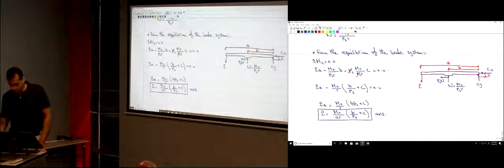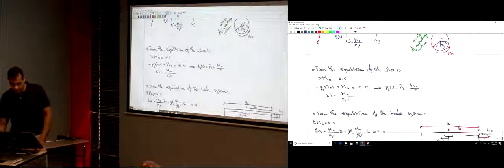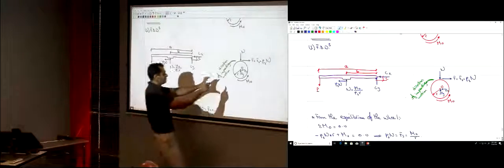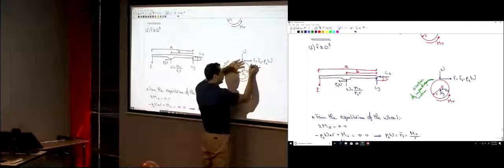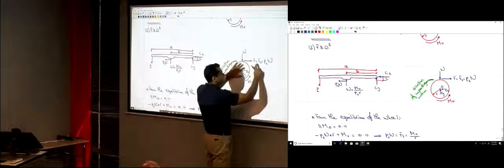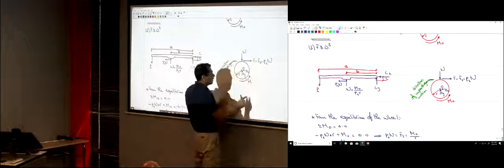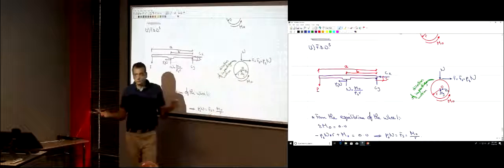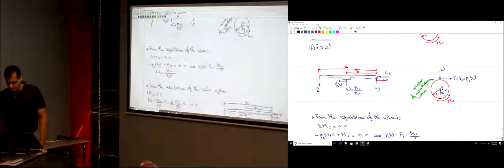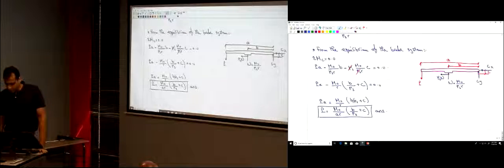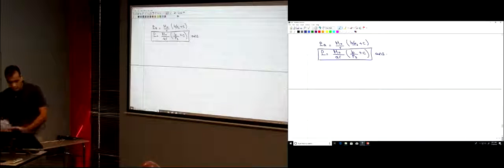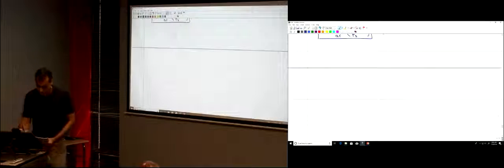So now, as you see here, when we had this circular shape with some moment m naught, this gets converted to a horizontal force, a frictional force, of m naught divided by r to be in equilibrium. I'm just going to use this now in our new discussion. We have a new topic now in friction.